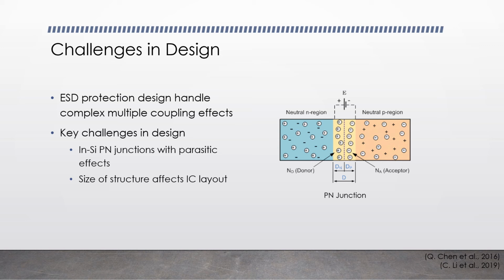Second, the in-silicon ESD protection structures are often large, in both core silicon devices and metal interconnections, to ensure robust ESD protection. They not only consume significant silicon area, but also cause difficulty in IC layout. The trend of IC nowadays is scaling down, so the in-silicon ESD protection is not adapted to the development of the industry, and a new on-chip ESD protection method is needed.